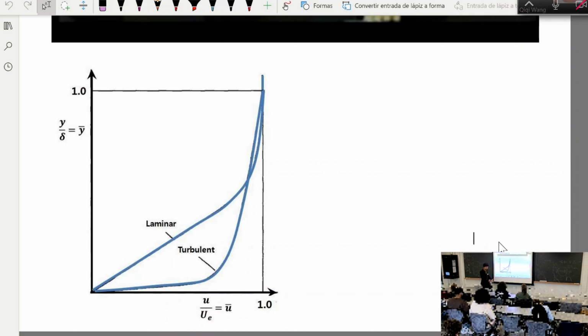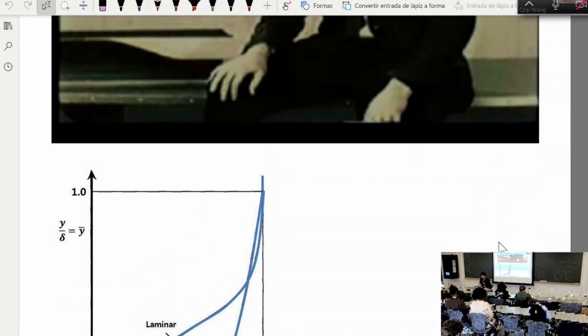So that's much harder to push against towards separation. So the two consequences of turbulence, I think, important to just know conceptually, is that it increases friction and heat transfer. That's one. And two is that it's more resistant to flow separation. I think these are the only two consequences you need to know about turbulence at this level of class.